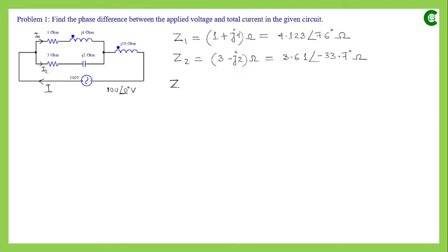Now with this parallel connection, since this inductor is connected in series, finally if we assume that the net or equivalent impedance of this whole network is Z, then in that network, as we can see, Z1 is in parallel with Z2, and then the impedance of this path, since this is connected in series, will be simply added as per the rule. Now if we first find the equivalent impedance of this parallel branch, then as per the rule it will be simply Z1 multiplied by Z2 divided by Z1 plus Z2, and then with that, since this is in series, this will be added.